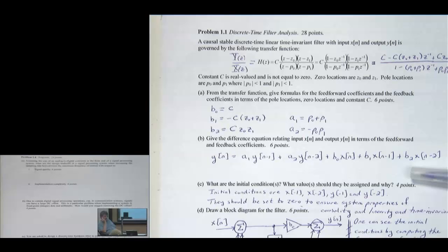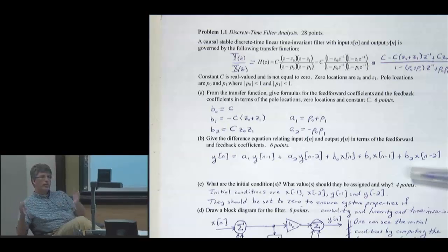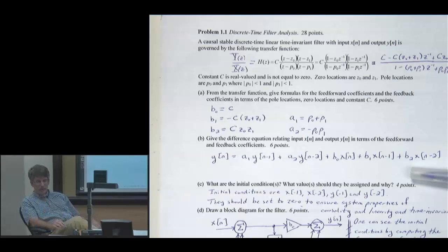Go ahead. Well, if there's noise, then there's a higher chance of sampling noise, but you use a filter to remove the noise. That's right. So more noise is getting through because you're at a higher sampling rate. Wasn't the noise getting through anyway, but aliasing? Right, exactly. The noise is already getting through, it's just aliasing into your band of interest. Now at least you've got a big chunk of that noise in a band outside of your frequency range of interest. That's actually a good thing, because now I can filter that out.